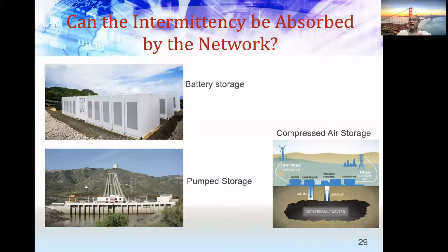The lower right-hand side is my compressed air storage project. There are some pilot plants being built all over the world. Germany has some, I know the US is building some. But what happens there, during off-peak hours, you use electricity to compress air and dump it into a sealed space. Could be a salt mine, could be some mine which is sealed, doesn't leak any air out of it. And hold it there. During peak hours, you release the compressed air to supply a gas turbine.